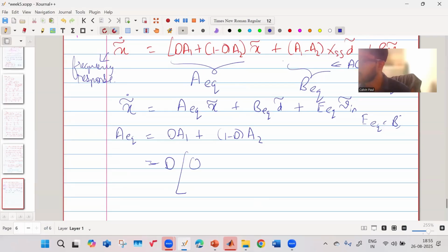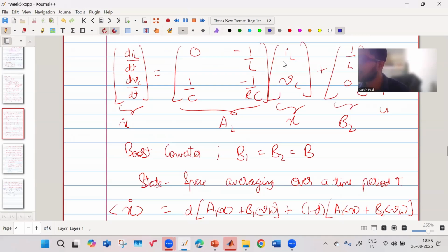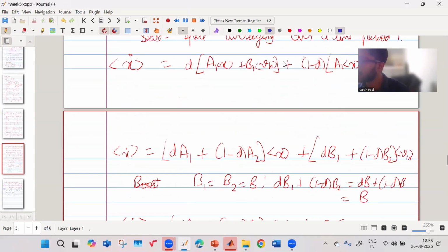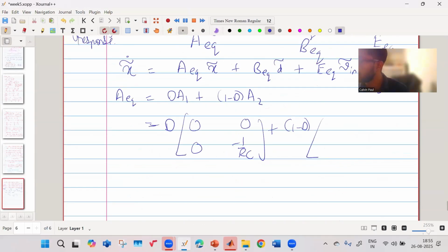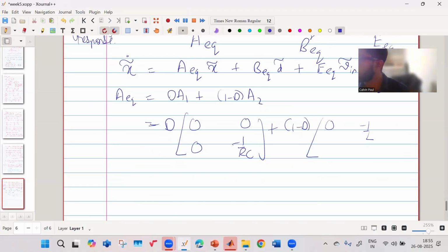Your A1 actually is 0, 0, 0, minus 1 upon RC. And your A2, let us check, A2 is what? 0, minus 1 by L, 1 by C, minus 1 upon RC. So what is your A equivalent?